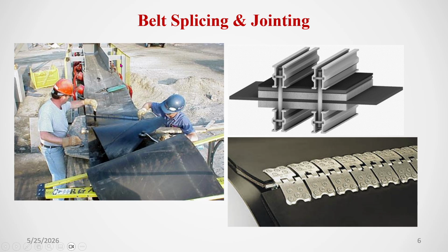You see, vulcanizing can be of two types: cold vulcanizing and hot vulcanizing. In cold vulcanizing, solutions are used and the two belt materials will be joined. In hot vulcanizing, we weld our joint with solution, pressure and temperature.